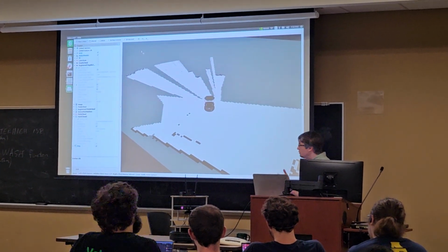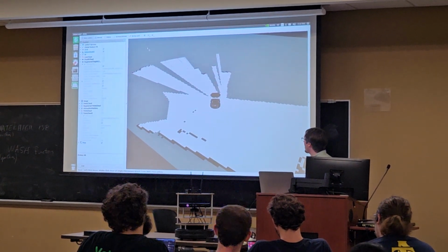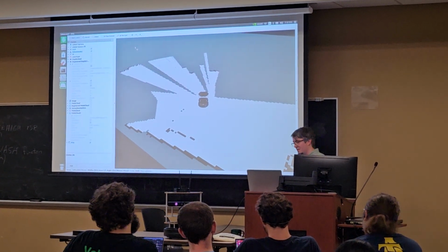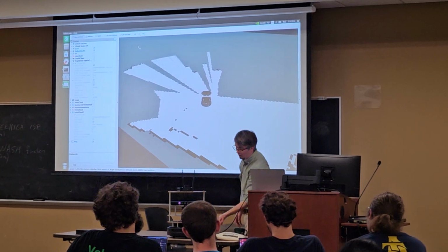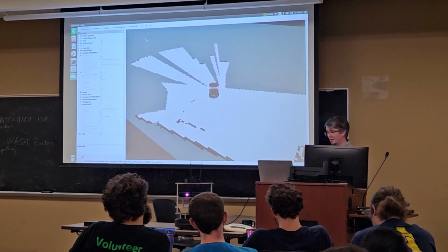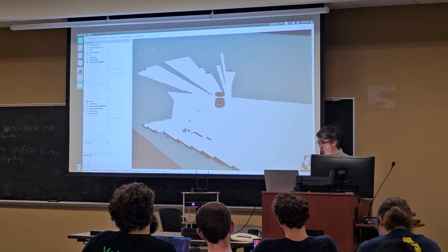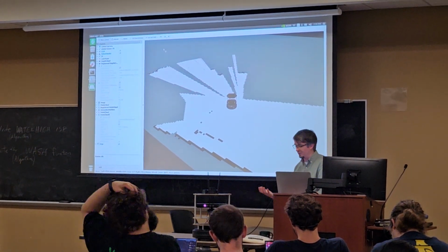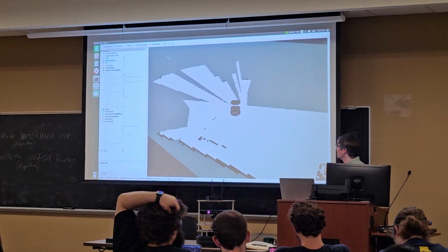And you can just use G-mapping on any robot that has a laser scan and odometry information. That's what's published from the robot. As I pushed around, the base publishes twist messages that are this odometry information from it moving.